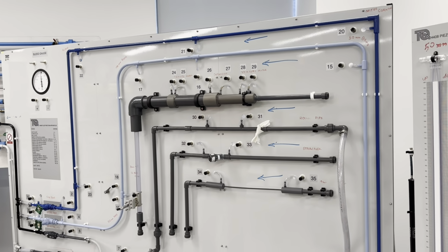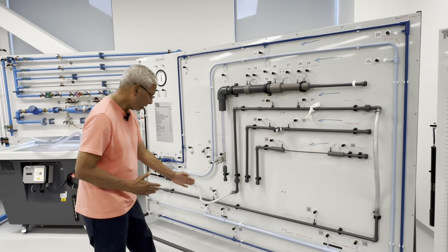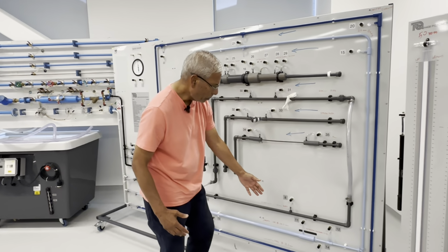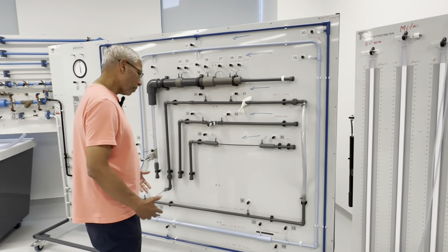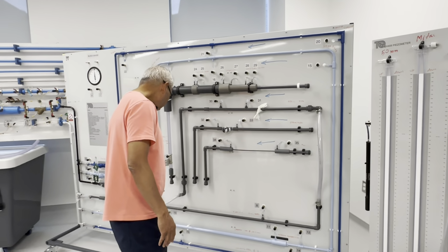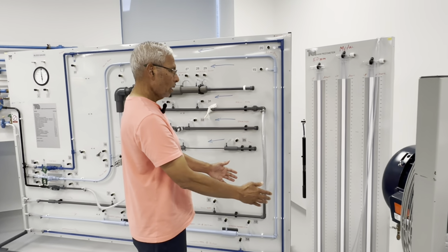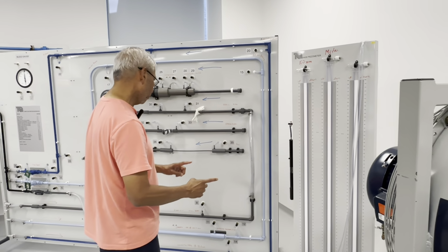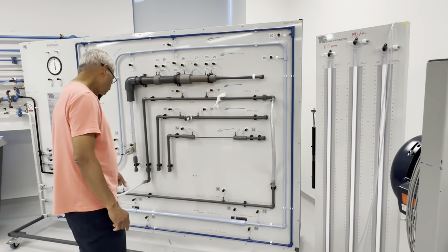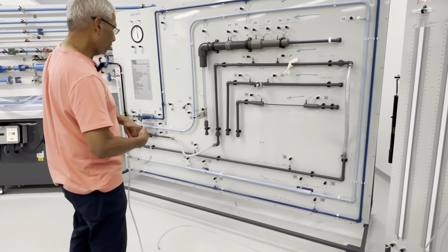What is a pressure tap doing? We're trying to measure the pressure head in the beginning, 10, and also the pressure head when it is leaving, 11. So now, how are you measuring the pressure head? We use a piezometer, which measures the pressure differential at point 1 and point 2. For example, point 1 is 10. We take this piezometer tube and we connect it.